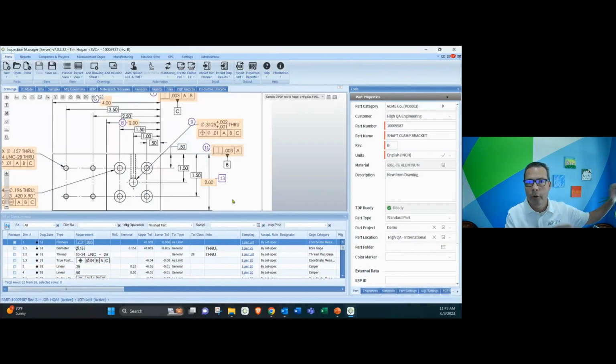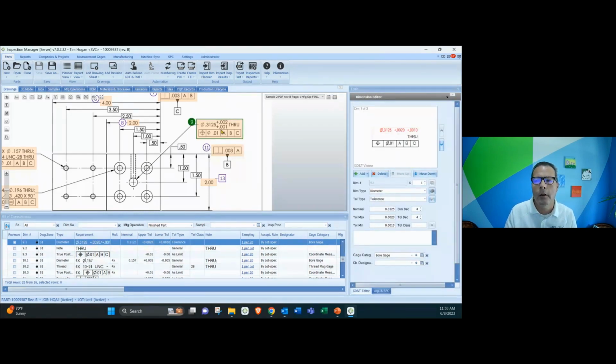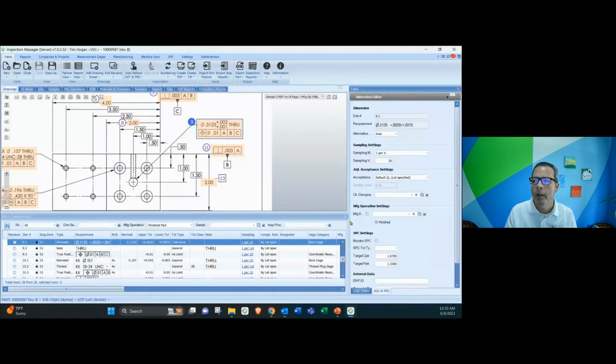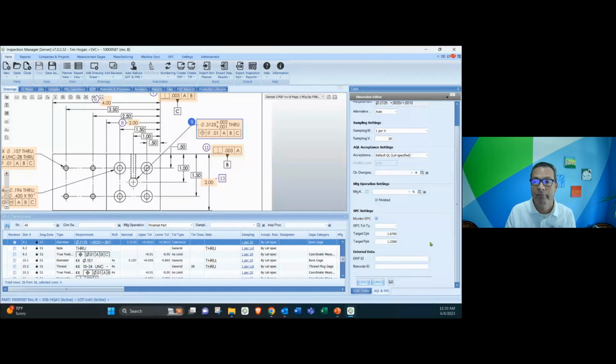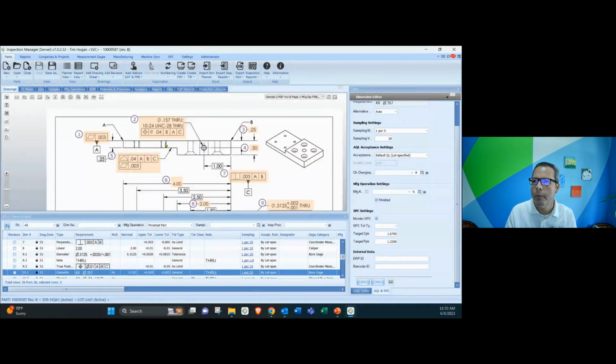If you want to run them for 2 years and then go back and see what it ran 2 years ago and compare it to today, the data is already in the database. All you need to do is tell it you want to look at it. And we're going to do that right here. It's very, very simple. This is where we started. So when we first started and ballooned it, right down here, there's a tab we did not click on before called AQL and SBC. And all we're going to do is click on this little box right here that says monitor SBC and hit save. That's it. Okay, I'm going to do that on a few dimensions here. We'll grab 3 of them here just so it looks a little better. And actually, let me grab this one up here.